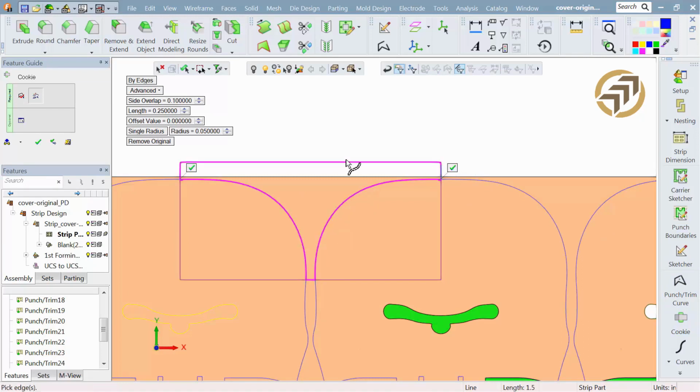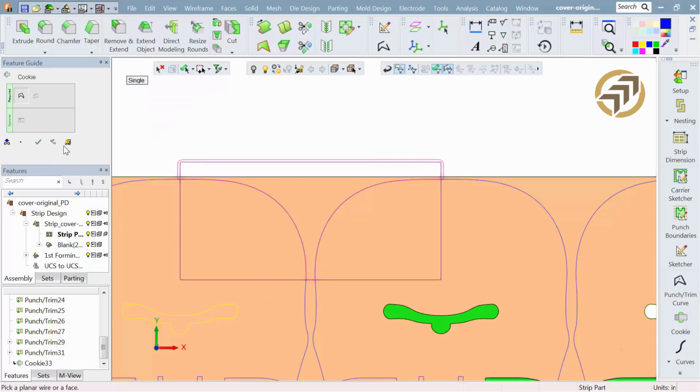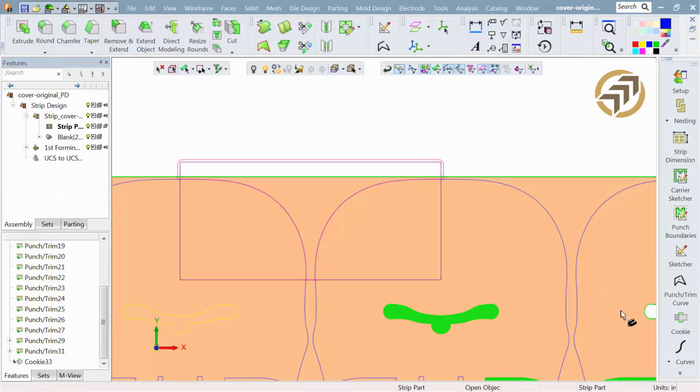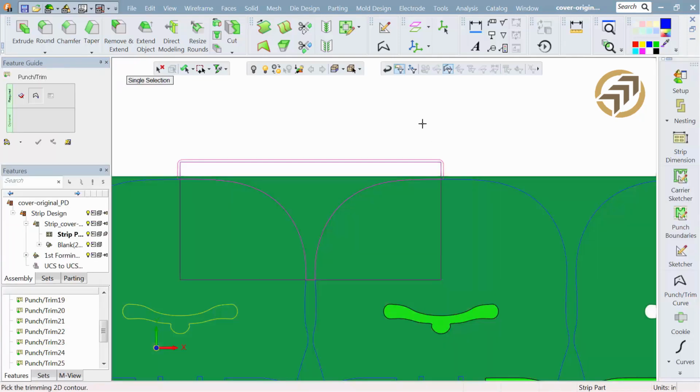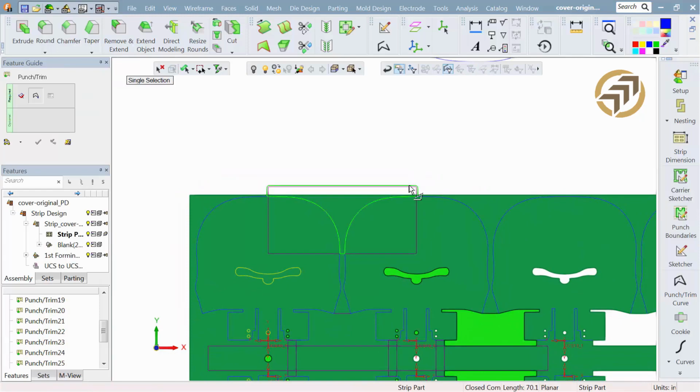Now in this case I picked that edge, but what I want to do is establish a distance around it. So I'm going to extend that edge, and the idea behind this is I want to create an overlap. That way the punch on one edge will shear off the other edge. Alright, so now I know I'm going to clean up that outer distance along the outside of the coil. That looks good. That's what we want to punch.